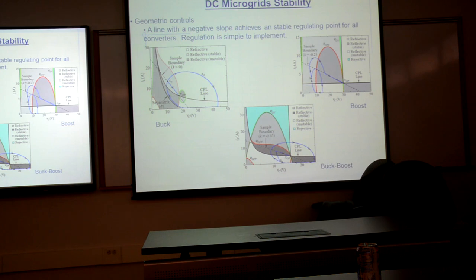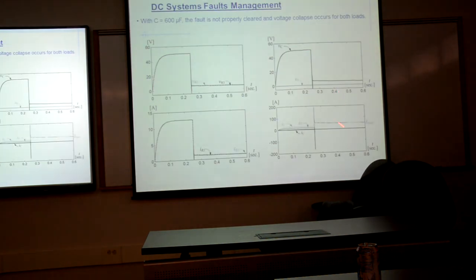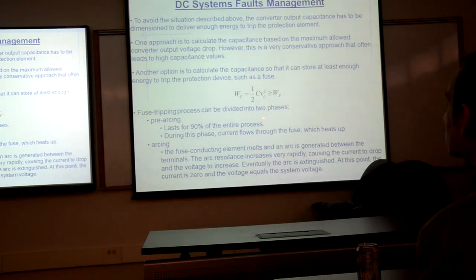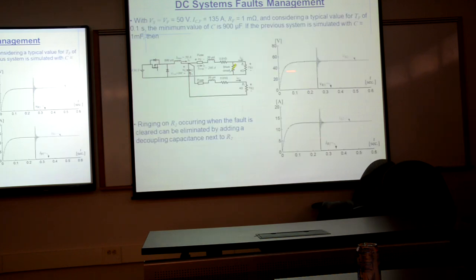The other approach is to have adaptive control, to keep track of and have very good control of the duty ratio and the frequency of the buck converter. I have an example here, with two nodes connected to the same buck converter. We can clearly see the voltage without the introduction of the converter, and after the introduction of the converter including that adaptive control. Here are the equations; I will go a little over those equations. We get a pretty stable voltage and current after the fault and its clearance.